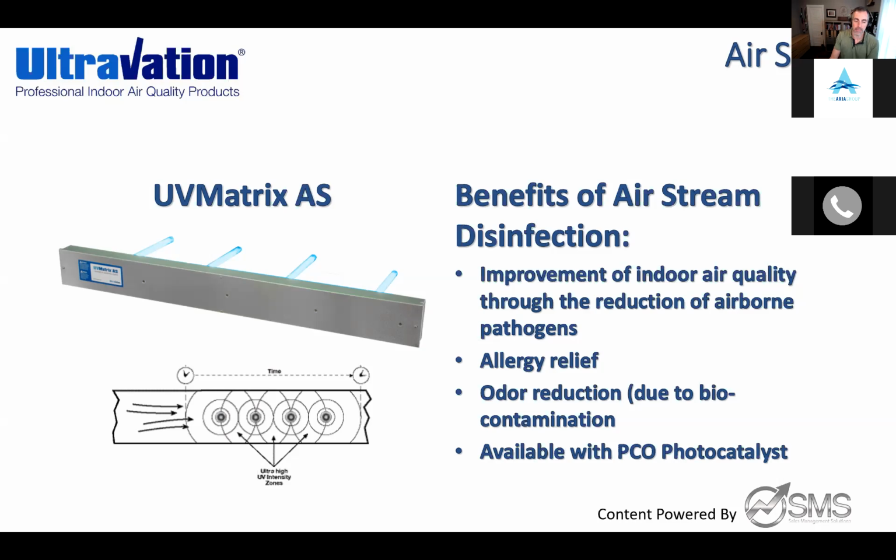So sometimes on some big jobs, if they're going for maximum disinfection rates, I've also seen these mounted one or two racks in a row after each other, because the air was moving so fast in such a big duct supply that we needed two or three of these racks in a row. So that's why the velocity matters so much too on the commercial application.